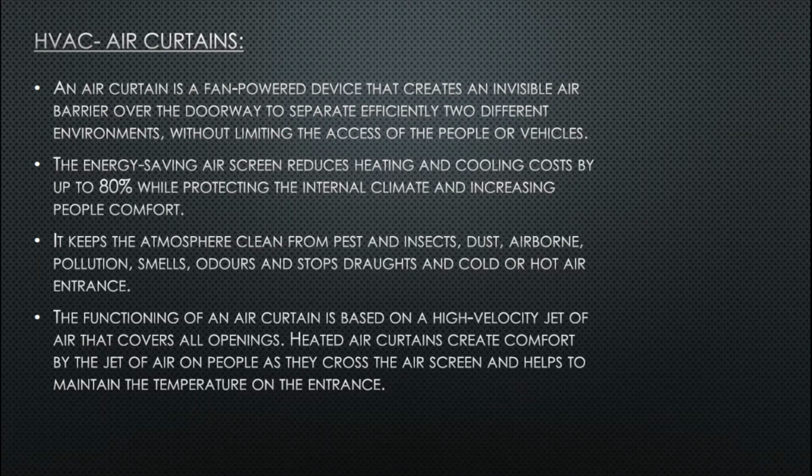An air curtain is a fan powered device that creates an invisible air barrier over the doorway to efficiently separate two different environments without limiting the access of people or vehicles. So it enables people coming inside and going outside without limiting the access, and the same applies for vehicles also.